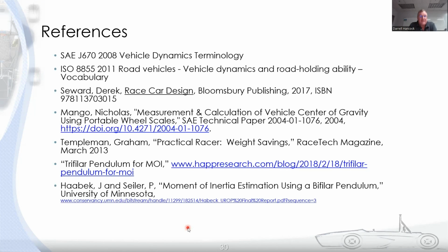You want the center of gravity to be as low as possible, but like everything else, there are compromises to be made. So do you know what those compromises are, have you understood them, and can you justify them? Okay. I think that's what most design judges would look for.